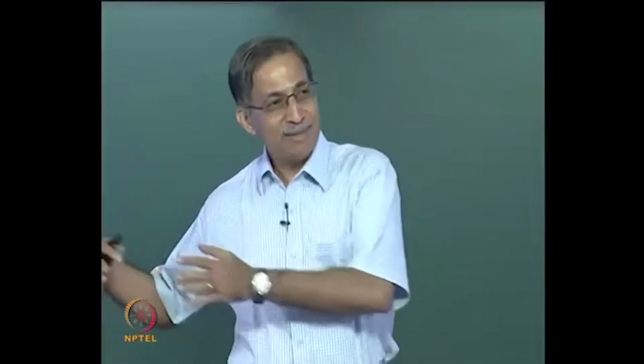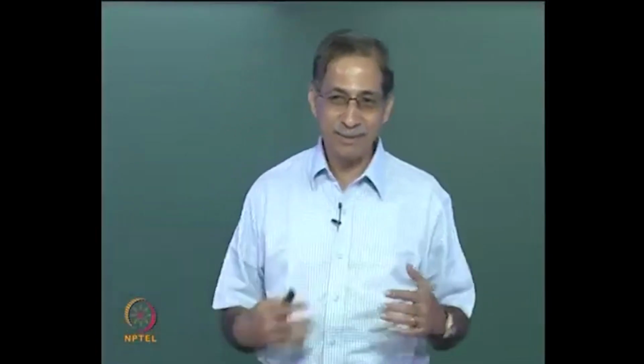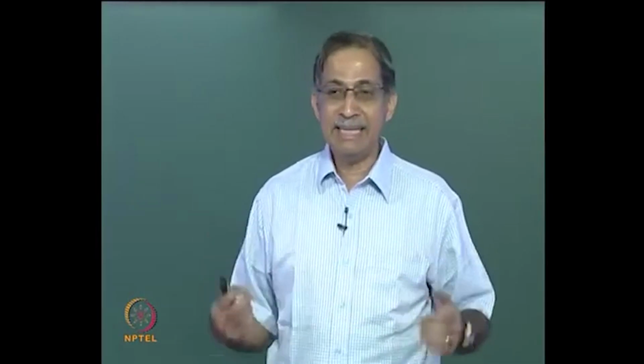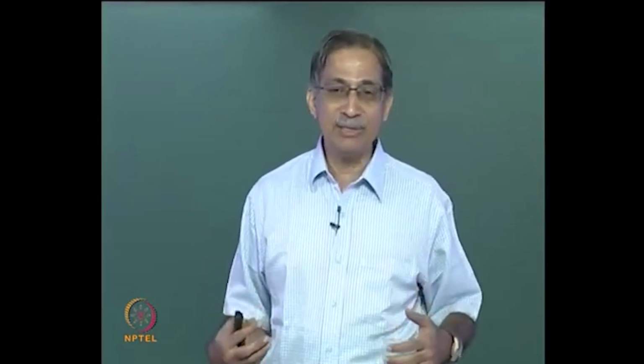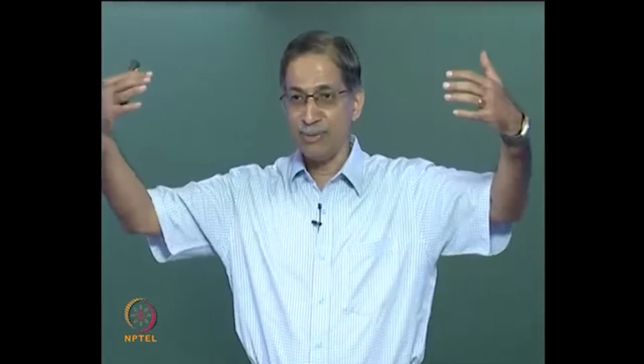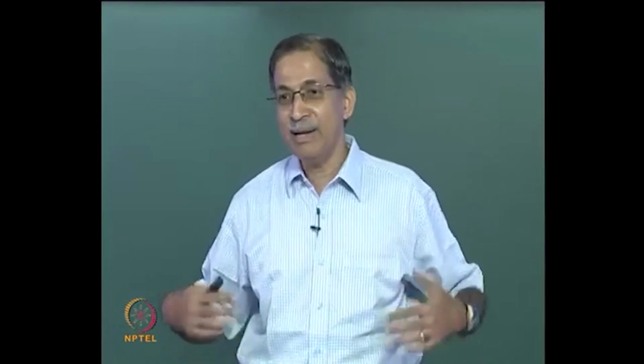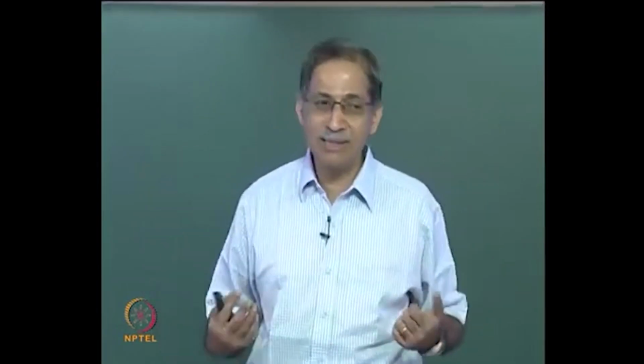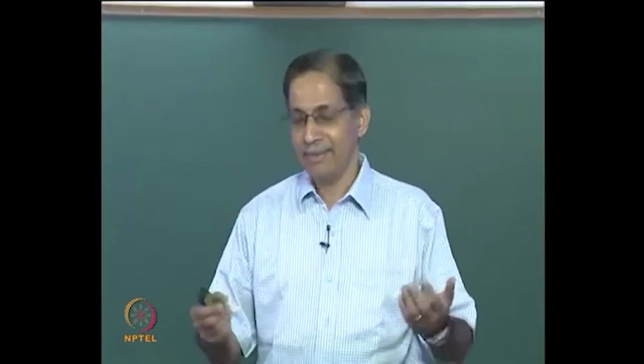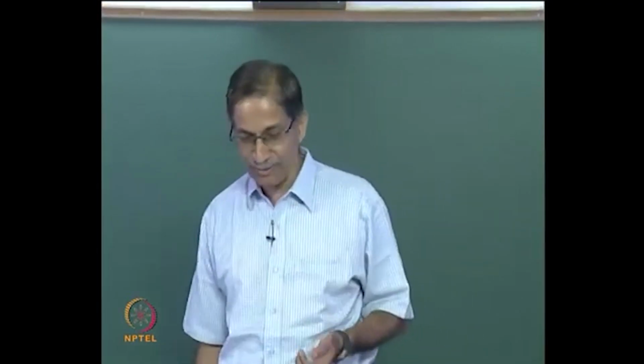Don't mix up problems. We are doing the conventional stiffness method. TF comes in the flexibility method, so it's easy to get confused. You remember that Ti enables a transformation from the global axis system to the local axis system, both for forces and displacements. Now we are trying to switch from the local to the global. So what's the transformation you need to do? There you are, Ti transpose, that's all you have to do.